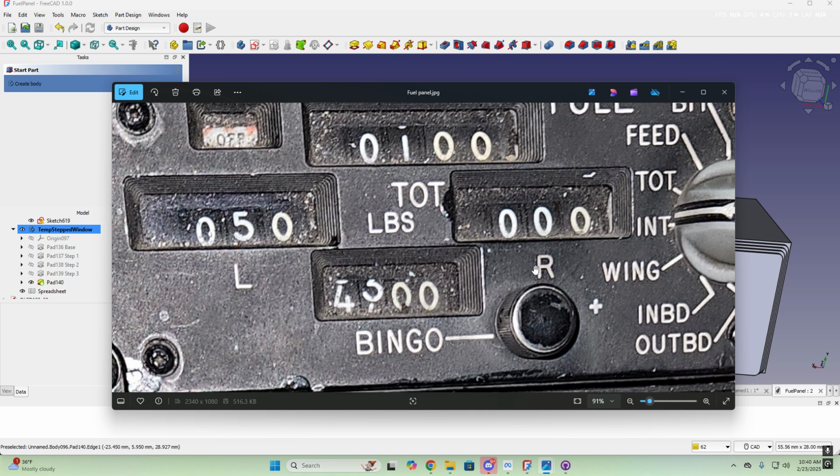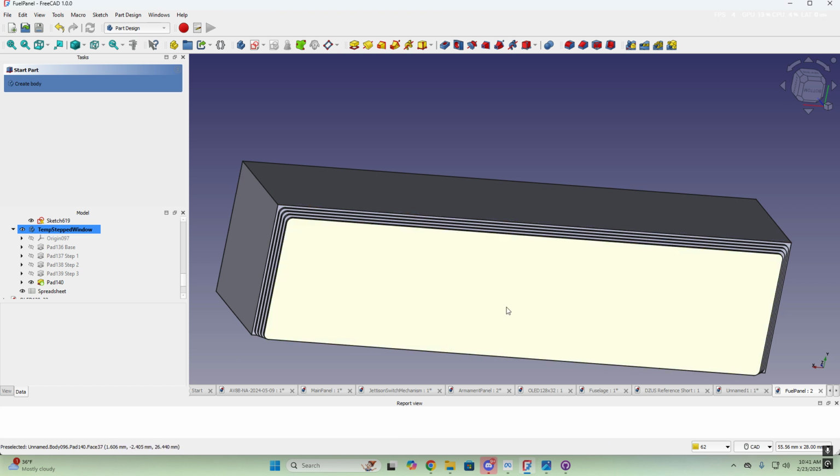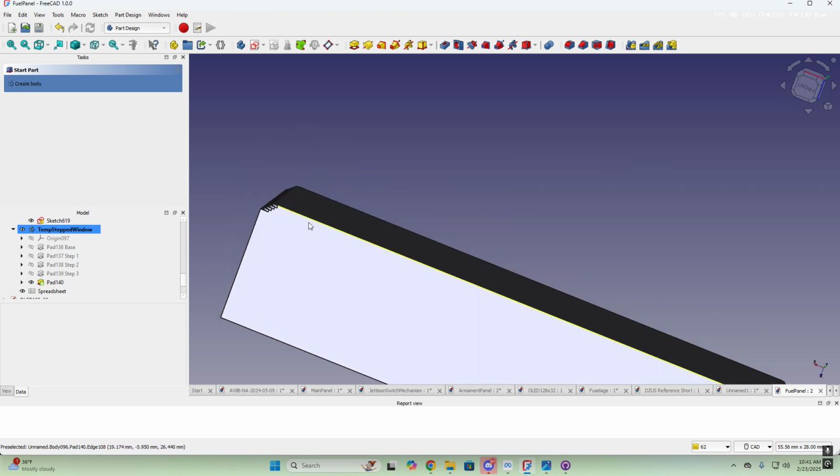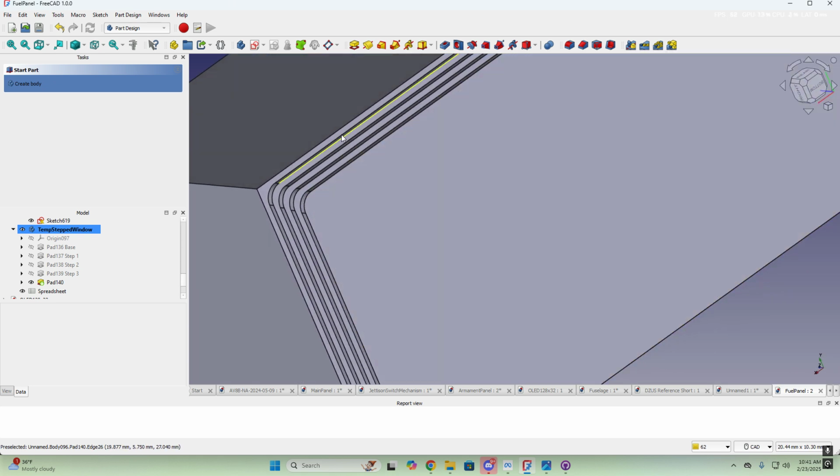And I think what they probably did is they machined a bunch of windows, each one being smaller than the previous one. And the way this window works is the bottom dimension is always the same, but the insides of the sides step in and the top steps in while the bottom stays flat. So you sort of have this effect. Here's the stair-step effect. You can kind of see how this bottom here is flat, but the sides step in each time and the top steps in each time.